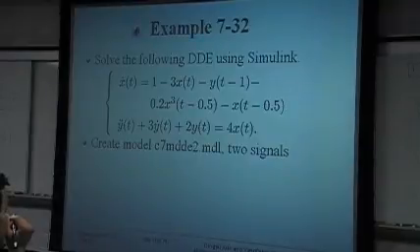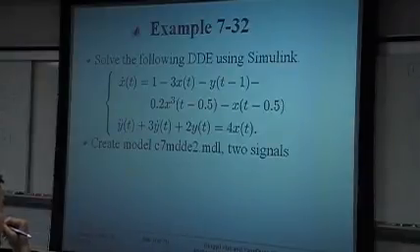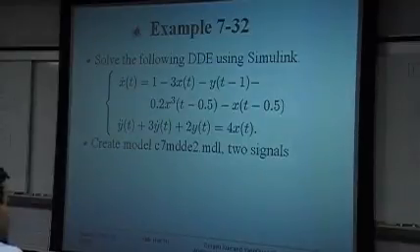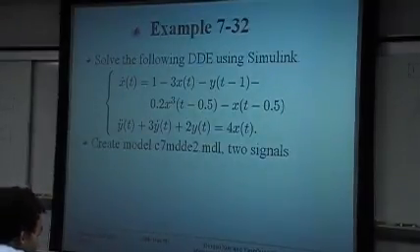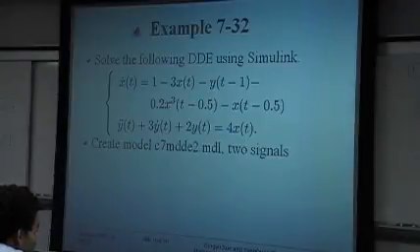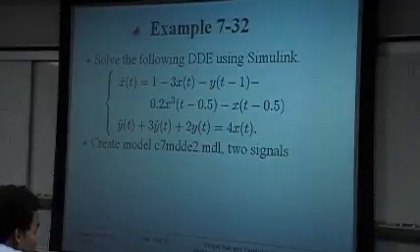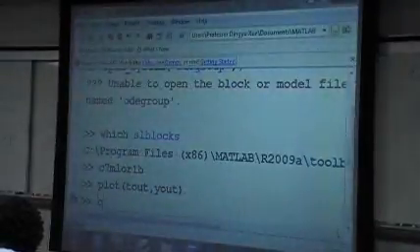Okay, so u is equal to x(t minus 0.5). Because you have connected this one here, u should be this signal, and this signal happens to be x(t minus 0.5). Here we can also write 1, but it is not necessary because u is a scalar signal. Also, if you are happy, you can use brackets like this. It is the same. So these kinds of notations are all acceptable. This is the model I created.